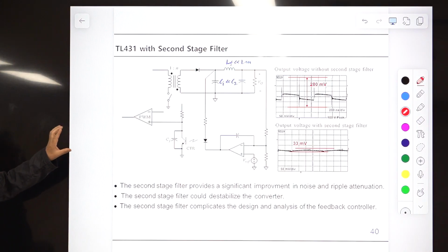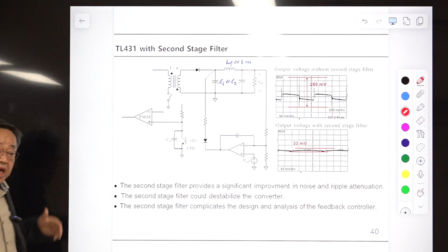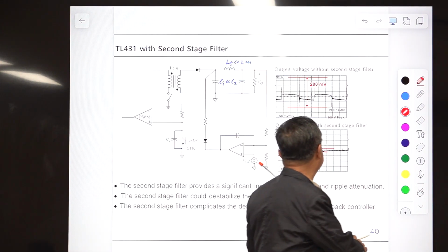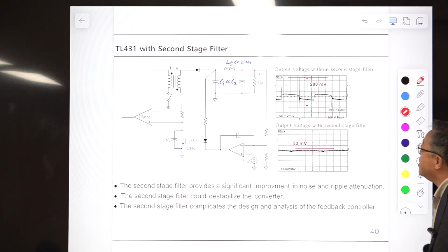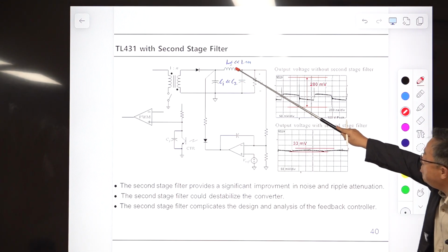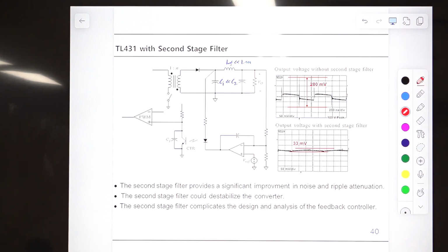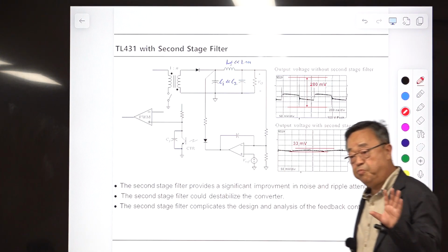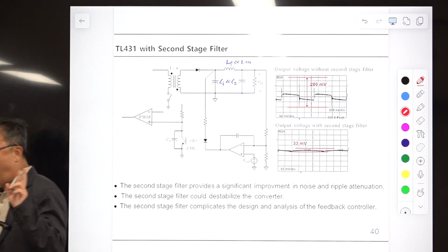Okay, so this is very bad. Okay, you should reduce this. All right. So this causes the EMI problem, and output is not a DC anymore. So this is a huge spike, and just adding this one and this one, very small ones, you have a 2-stage filter, and with that, our voltage is changed from here to here. The peak to peak value of this, including this switching spike, is about 1/10 of this. Okay, so this is a dramatic improvement from using a two-stage output filter.